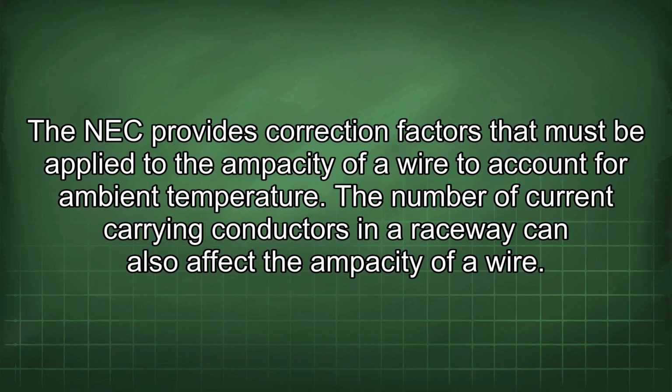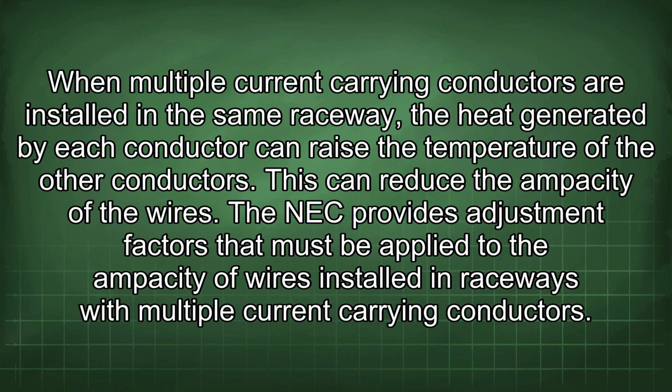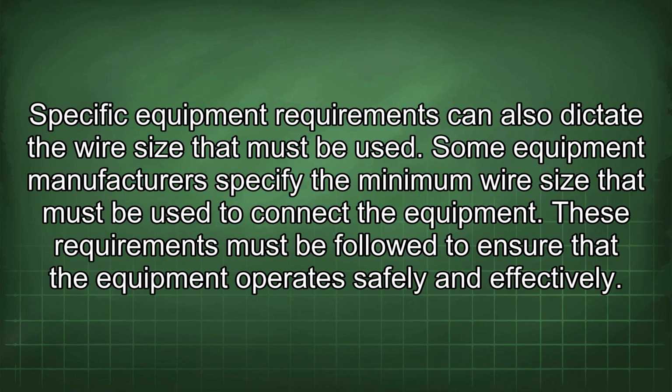The number of current carrying conductors in a raceway can also affect the ampacity of a wire. When multiple current carrying conductors are installed in the same raceway, the heat generated by each conductor can raise the temperature of the other conductors. This can reduce the ampacity of the wires. The NEC provides adjustment factors that must be applied to the ampacity of wires installed in raceways with multiple current carrying conductors. Specific equipment requirements can also dictate the wire size that must be used.